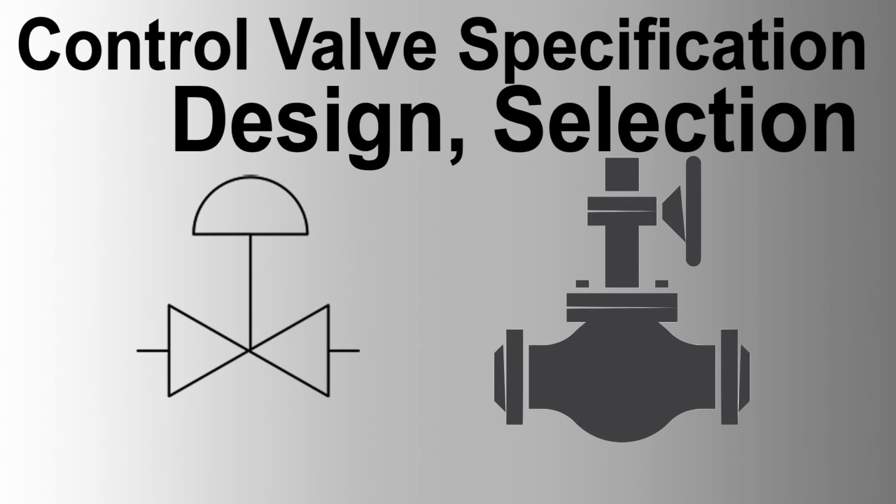5.2 Piston actuators. Application: long stroke or high thrust requirements. Design: double acting with external volume tank and trip system if specified. 6. Accessories. 6.1 Positioners. Type: smart positioners with HART protocol, stainless steel construction. Capacity: sufficient for pressurizing and venting the actuator, weatherproof, IP66.